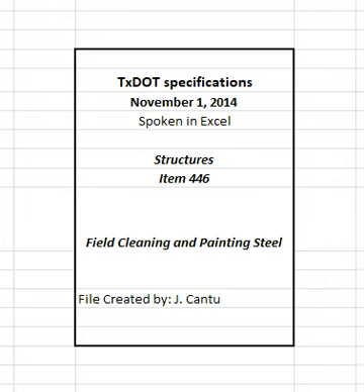When required on the plans, submit a containment plan and engineering analysis showing the loads, including wind loads, added to the existing structure by the containment system and waste materials. Verify the forces and stresses induced in the members from these loads do not result in overstress of the members. Have a licensed professional engineer sign, seal, and date the submittal. Provide containment during all cleaning and painting operations of existing steel structures. Obtain approval of the constructed containment system before beginning cleaning and painting. Unless otherwise shown on the plans, construct and maintain a structure meeting the following minimum requirements.